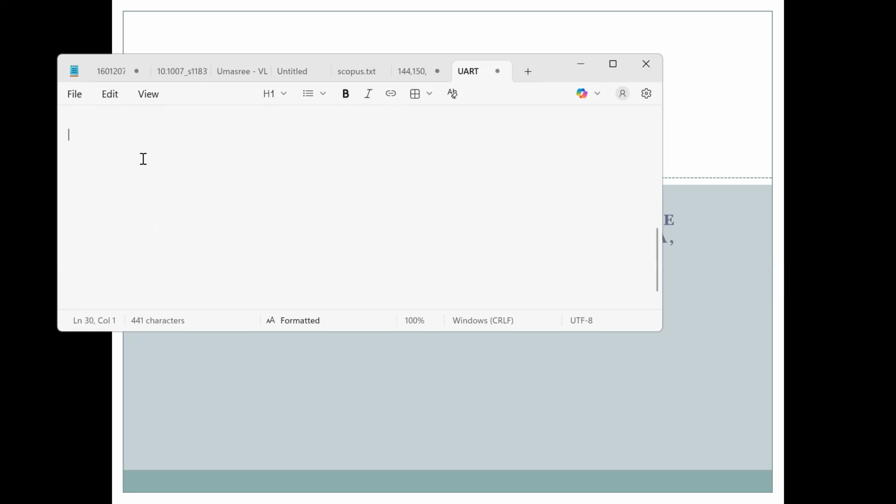As per the given specification, your F baud is 9600 bits per second, and 8 data bits with 1 stop bit. So you need to operate your UART in 8-bit UART mode, which belongs to mode 1 of operation.